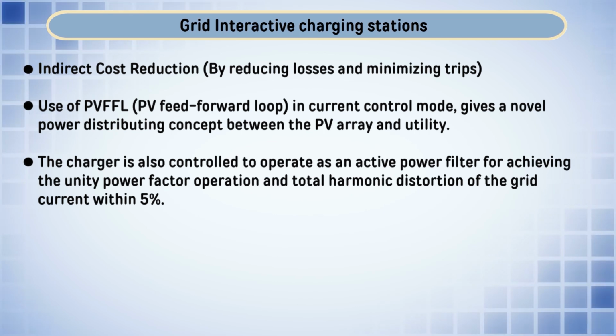It says if you are injecting power or drawing power, you are not allowed to inject harmonics more than 5%. So, we have to follow these standards.